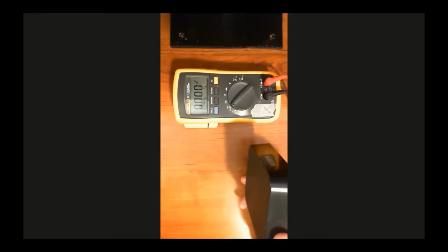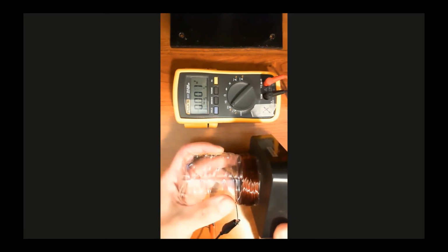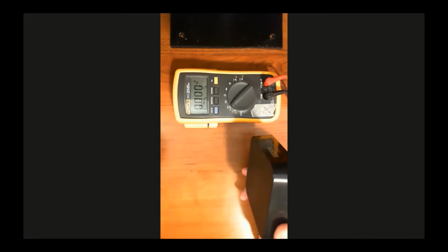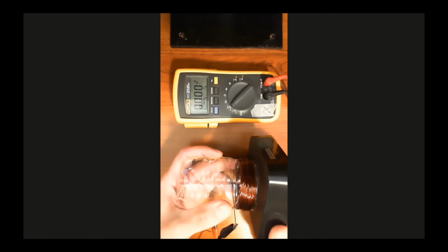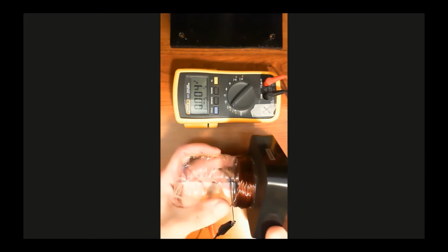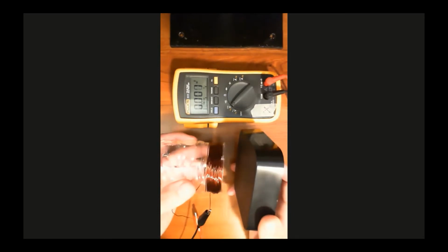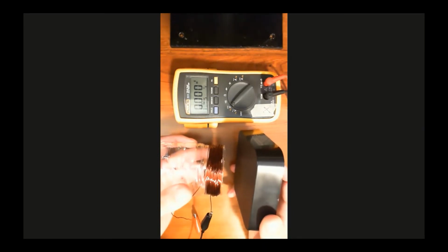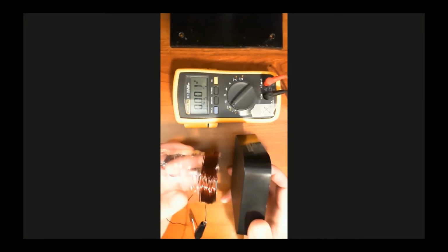So I'm going to hold the magnetic field stationary. I'm going to move the coil of wire. So I'll move it close together. And I saw, I think, 11 millivolts that time, and now apart. I saw negative 15 millivolts once again. I saw 13 millivolts, negative 13 or negative 14 millivolts. So it seems that it doesn't matter which one I'm moving, right? So as long as I have motion, relative motion, we're going to call it relative motion. As long as I have relative motion between the magnetic field and the coil of wire, then I induce a